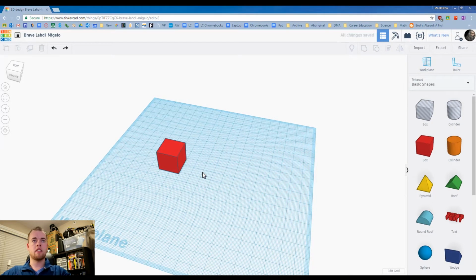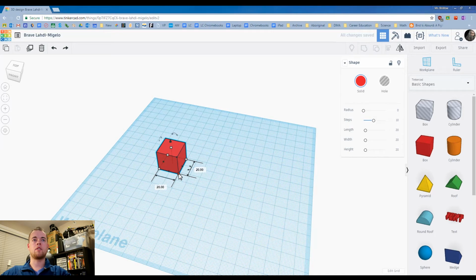So once again, I have my box, click on the corner square there, set my dimensions to 45 by 15. I am using the tab key to jump in between values, and then change my vertical distance to 2.5.